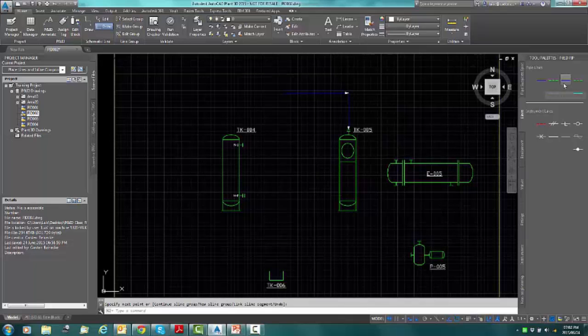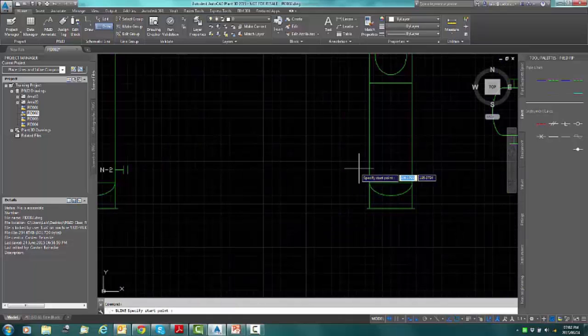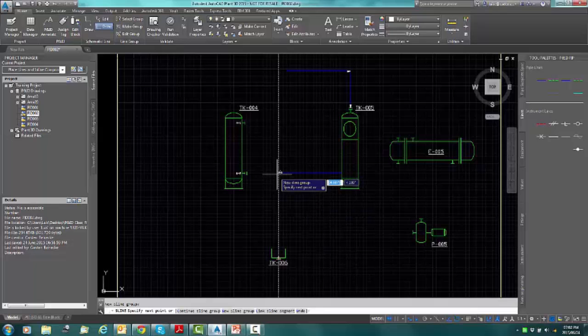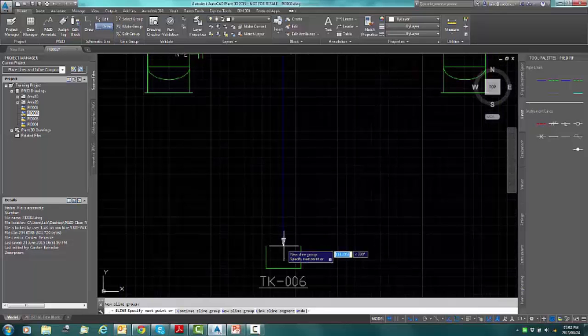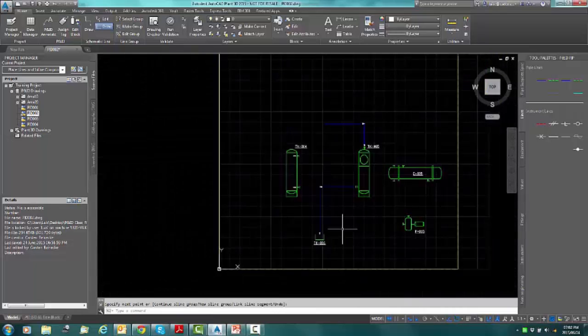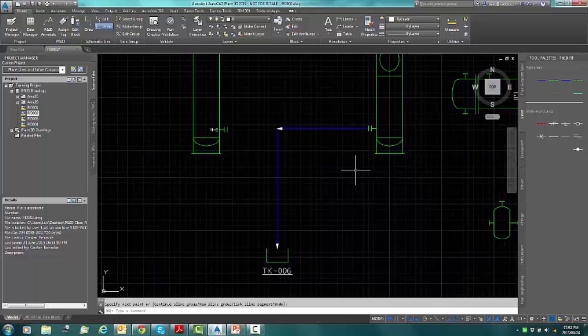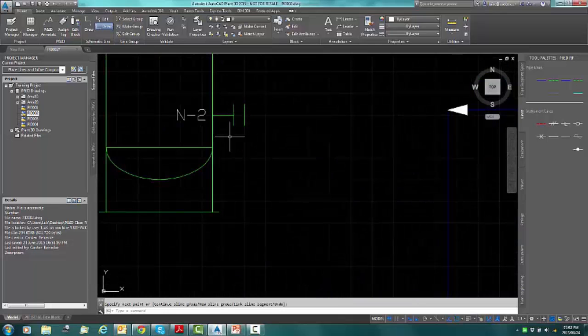I want you to select primary line segment again, this time starting from more or less down here at the bottom of the vessel. We're going to click. Again, I'm going to track, click, and like so, and enter once you're done. And notice what it did. It's added a nozzle for you automatically again. So you shouldn't really have to be putting in your own nozzles unless you are putting in a closed nozzle, so perhaps for expansion. This is a blind flange.